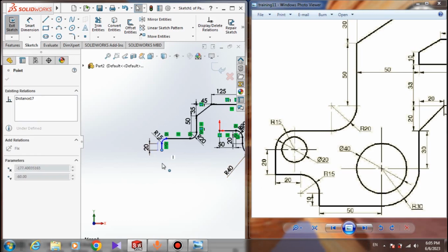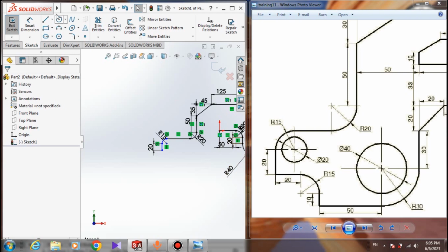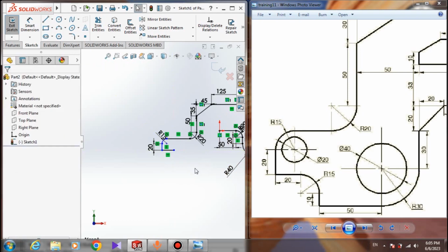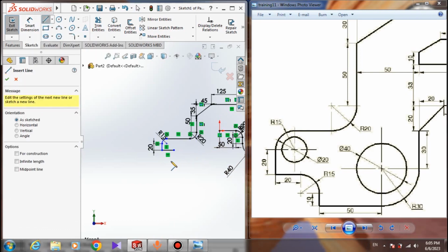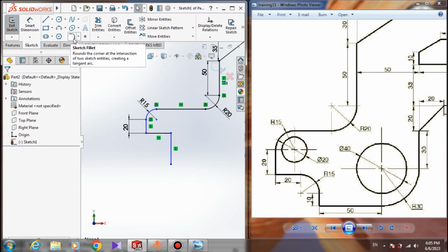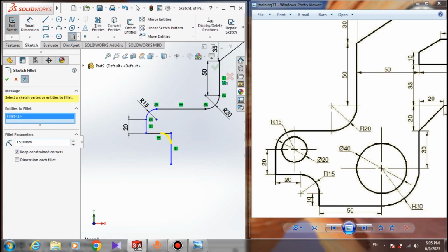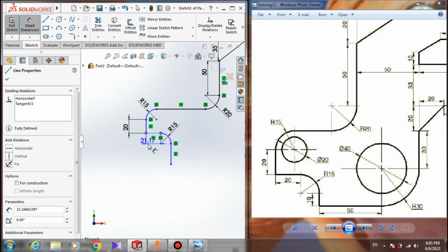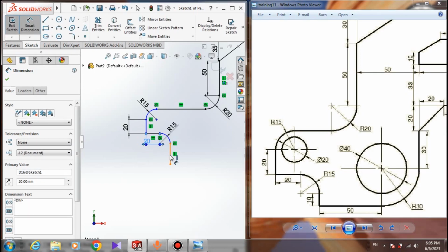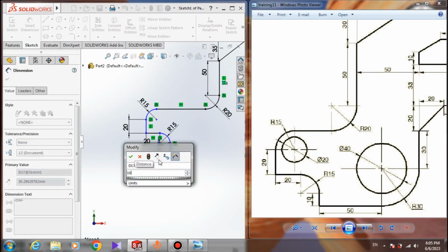Let's move my sketch a little bit. Here is okay. And then we have a horizontal line. So here I draw a horizontal line. Then we have a fillet. So I have to draw a vertical line. Now I have to apply the fillet. Here I choose fillet and I choose the point here. The fillet radius is 50 millimeter. Okay. And sorry, the dimension of the line here is 20 millimeter. And the dimension of the line here is 10 millimeter.